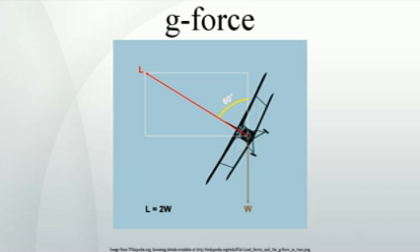In the same way, a negative g-force is an acceleration vector downward, the negative direction on the y-axis, and this acceleration downward produces a weight force in a direction upward, thus pulling a pilot upward out of the seat, and forcing blood towards the head of a normally oriented pilot.